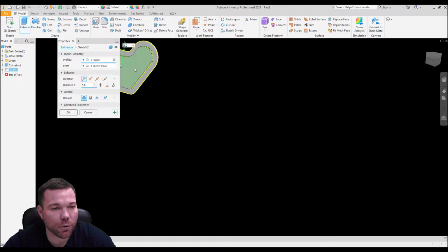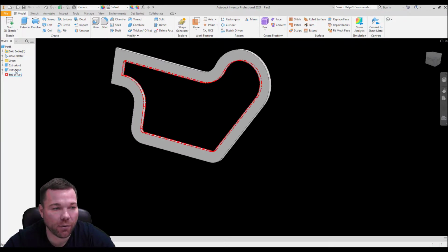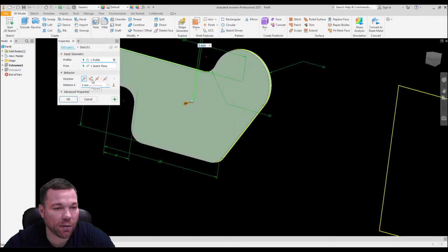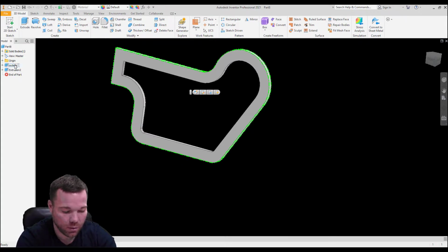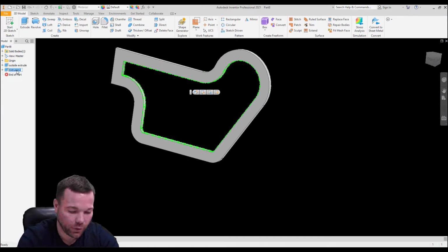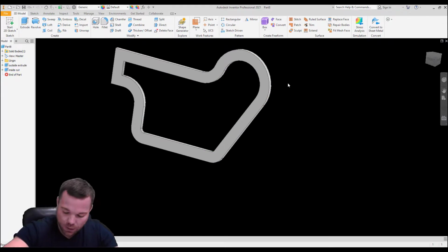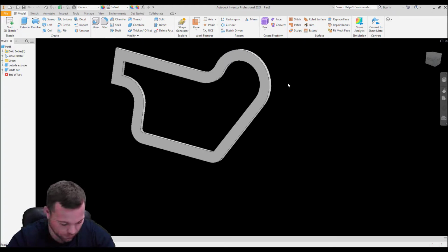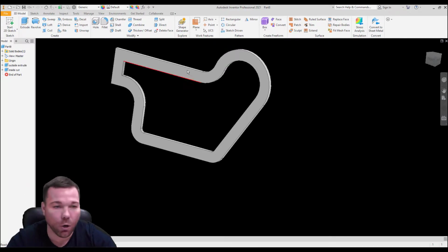So we're going to hit extrude, and I'm going to say through all, and hit OK, and there we go. There is our gasket. Of course, I would name this as, oops, outside extrude. Darn it. Always have trouble clicking on these. Inside cut. Okay. And then what it has us do here, after we extrude everything, it just tells us, okay, let's change the overall height of this thing just to see what will happen.